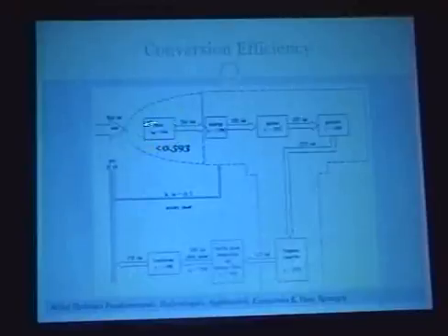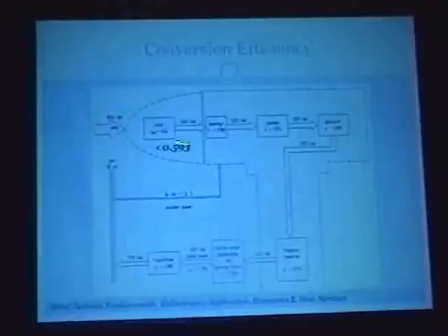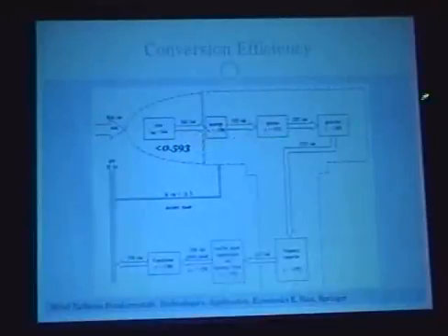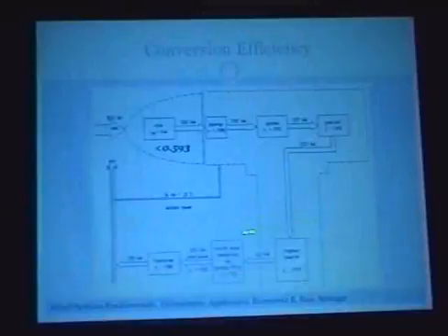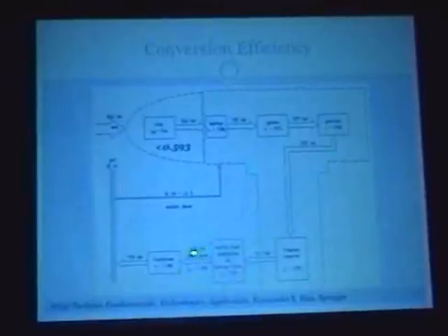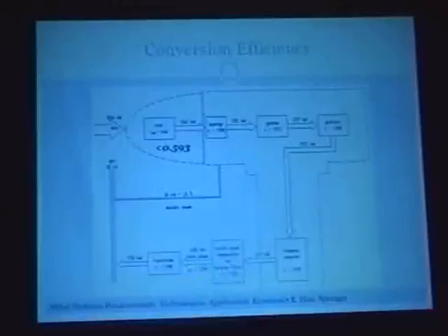And in this well-designed real turbine, you see that it's something like 44% of the power of the wind that's extracted. So if you have 3 megawatts of wind power subtending the area of the turbine, this particular thing is extracting 1.3 megawatts. Now, that mechanical power, of course, has to get converted into electricity, but let's go through the different steps here. Well, you have some bearings, and that's 99.6% efficient. You have some gearbox, some generator, and these are the generators that I talked about in the second lecture. And then you have some conditioning that makes the power more amenable to the grid, and the output of this whole chain is 1.2 megawatts, and you see that the overall efficiency is about 40%.